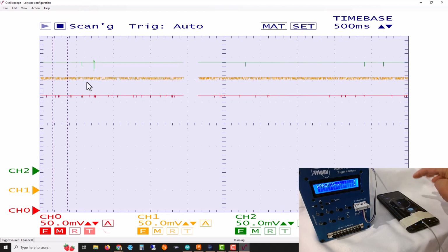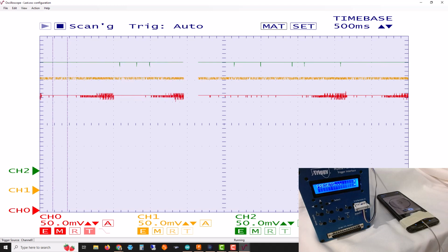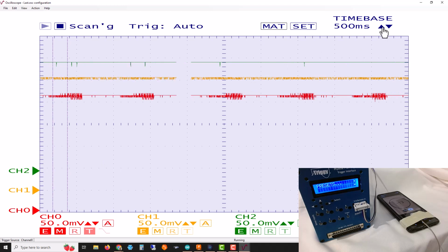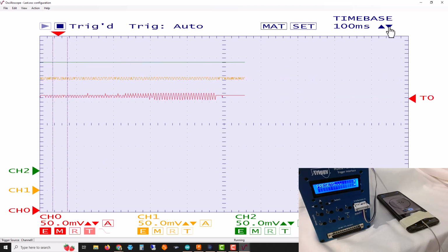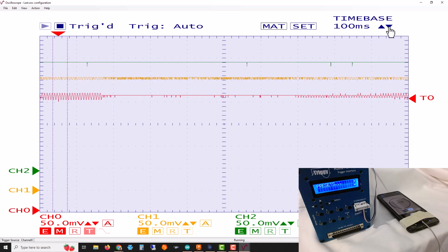But even with this very small signal from the phone's haptic interface, which I've just started here, you can see the signal on the red trace here. It's channel 0 or DAQ 0. If I adjust the time scale, you can see the quality of the signal. It's not perfect, but it's adequate to discern the frequency content and the approximate onset time of the signal. And this is a pretty small vibration. Accelerometers are really not meant for this small signal, but it is possible to capture it.